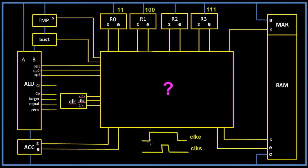But also remember from the clock video that it actually takes 4 clock pulses from the master clock in order to go through this one cycle of the clock enable and clock set. And you'll see that whenever we go on and look at it in Logisim. So the best way to understand the control section is to work through a full example.